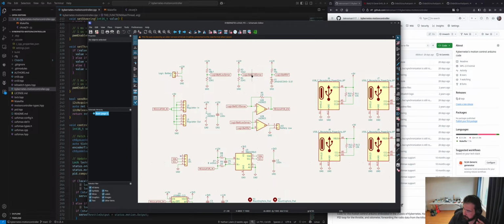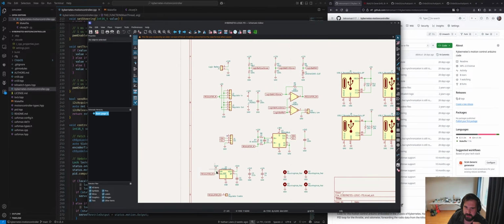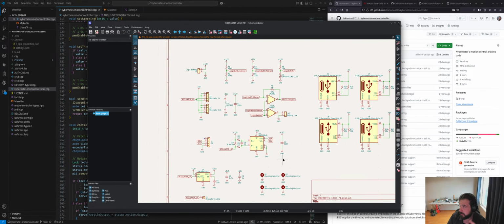If you go below 3 volts a cell, the whole thing just turns off the regulators and stops all the power draw off the battery, or at least almost all of it. Just a couple of microamps aren't handled, just because you need to supply power to generate the reference voltages.